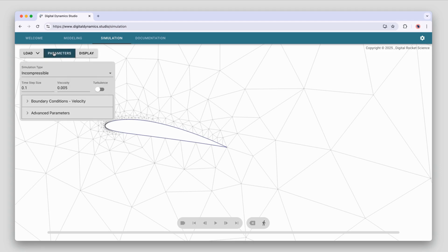For a real aircraft, like a real airplane, either a light airplane or a commercial airliner or something like that, the actual Reynolds number will be very high, tens of millions, whereas we simulated Reynolds number 1000 in the last simulation. But in a real situation, with real air viscosities and everything, the Reynolds number would actually be much, much higher. So let's simulate that condition. Let's change the viscosity to something lower, which means that the Reynolds number will be much higher. In this case, roughly 2 orders of magnitude higher.